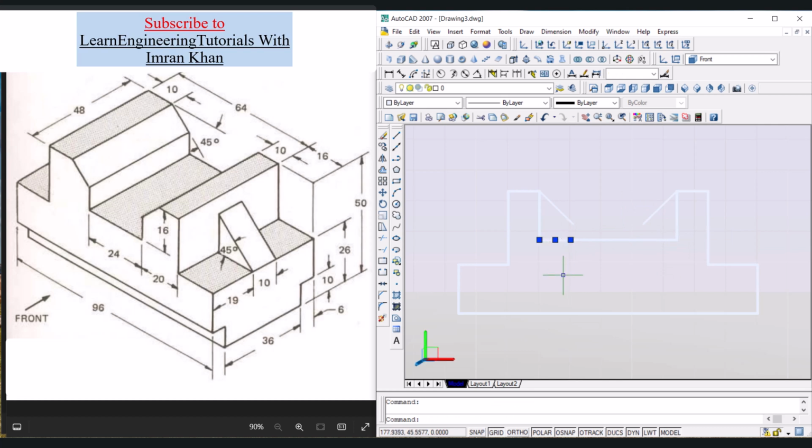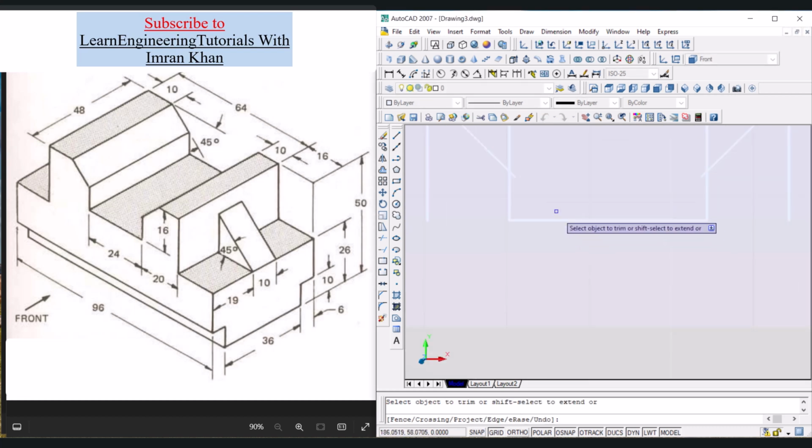Now we have to remove these lines and then try to join these lines. So click on line icon, click on this end point, move the cursor in the upward direction and click. Press enter, enter again, click on this end point, move the cursor in this direction and click.